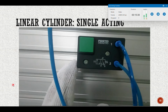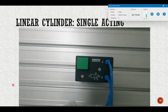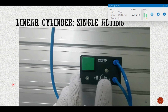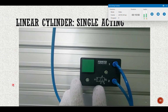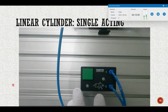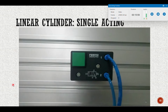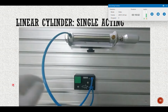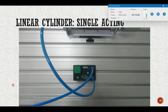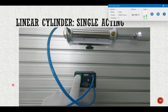Now what is the name of this valve? We can tell it by the circuit diagram. You see two rooms, which means you have two positions. And how many ports do you see? 1, 2, 3. 3 ports. So the valve name will be 3/2 direction control valve. This is used for single cylinder. So it is a 3/2 direction control valve with push button. When you push, it will activate.